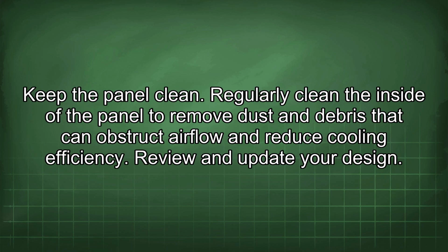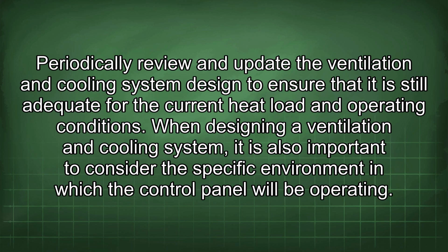Keep the panel clean. Regularly clean the inside of the panel to remove dust and debris that can obstruct airflow and reduce cooling efficiency. Review and update your design. Periodically review and update the ventilation and cooling system design to ensure that it is still adequate for the current heat load and operating conditions.